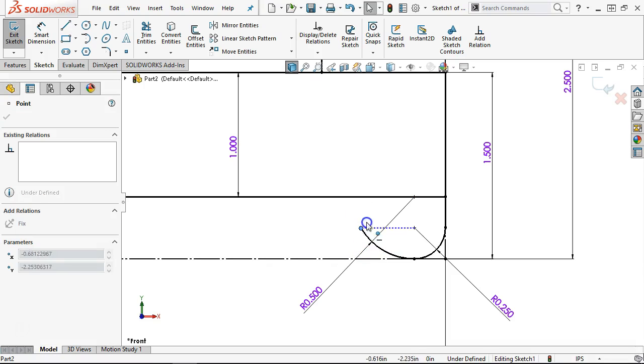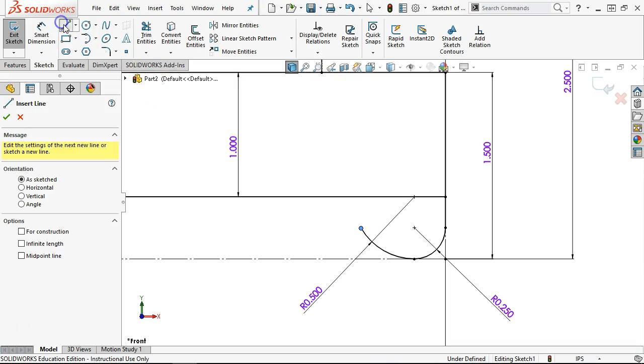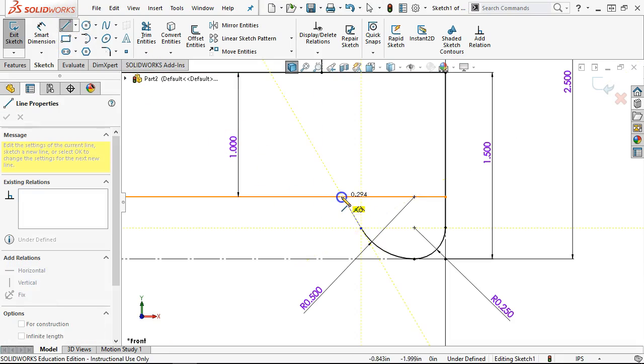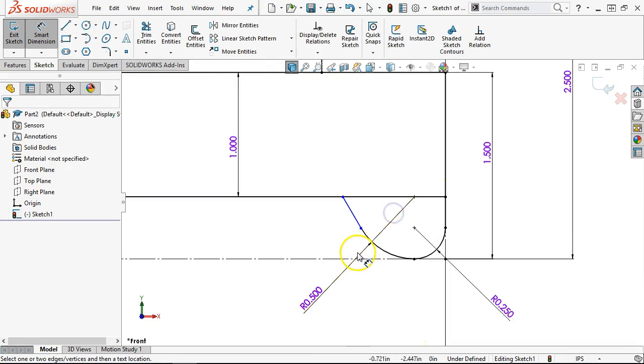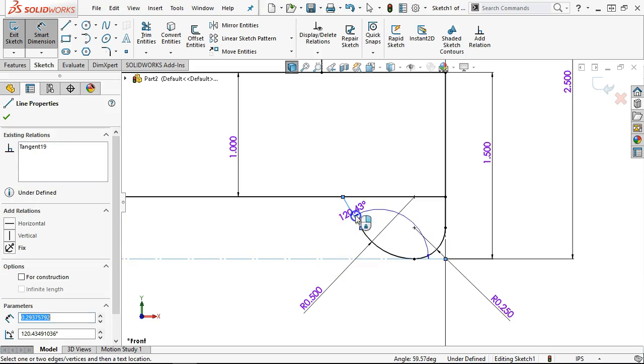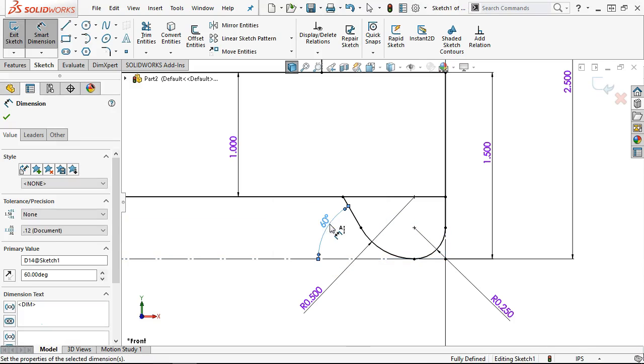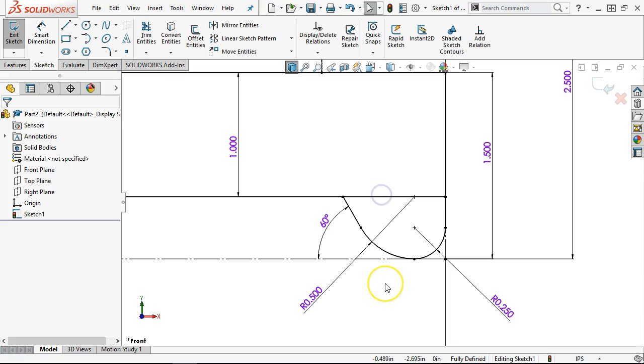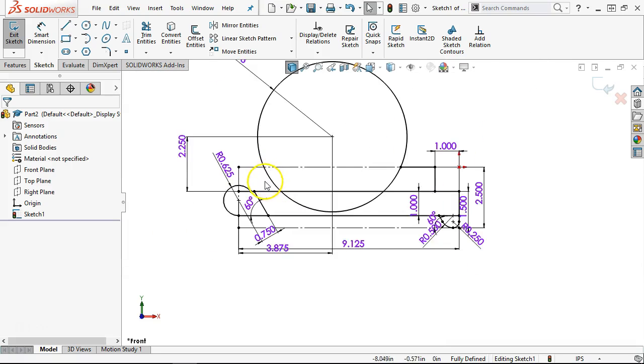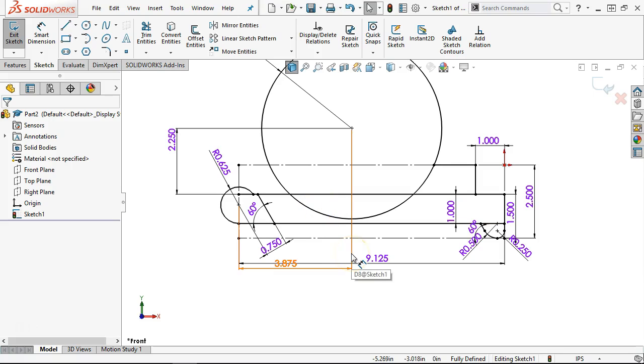All right, so nothing's moving or behaving badly. Come off with another line, and then see if we can get that 30 degrees in. Showing that off of vertical, so the adjacent angle would be 60. I can stay with the 60, and that goes fully defined. All right, so the question is, do we start trimming? Do we leave it? Do we start picking regions?